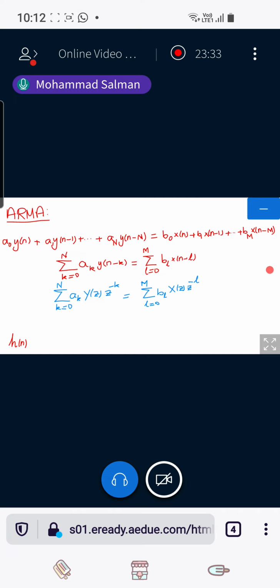And what I want is Y of z over X of z. So let's divide both sides by X of z. So here this is cancelled. What I want is Y of z over X of z. It is constant with respect to this summation over K, so I can take it outside the summation. So in this case, what is Y of z over X of z?